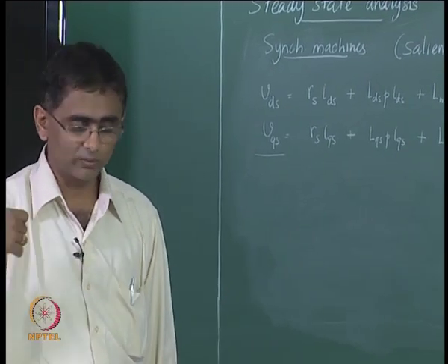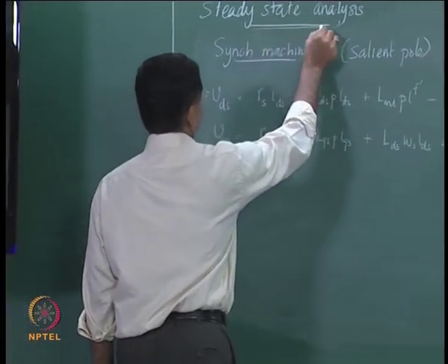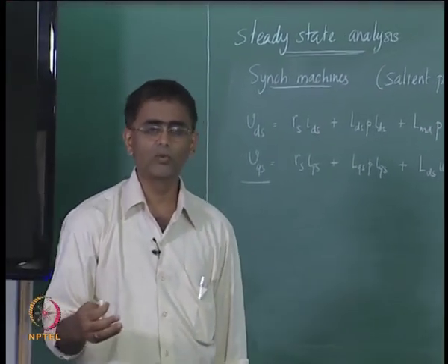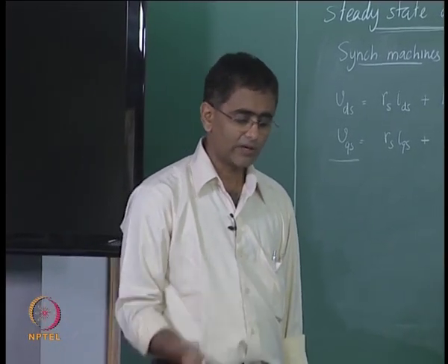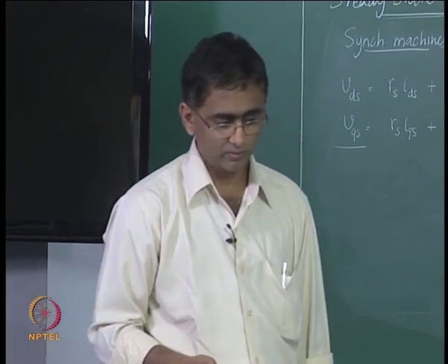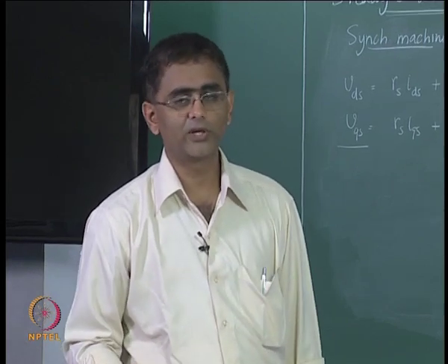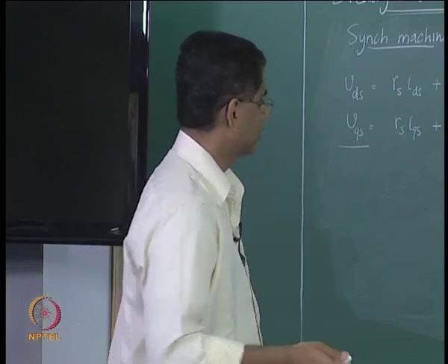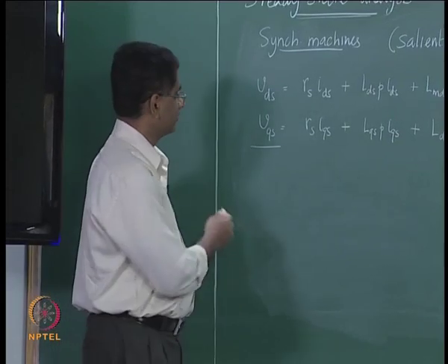The rotor is fed from the DC side, and under steady state it is going to carry a steady field excitation, which is not normally considered in the steady state analysis. In fact, if you look back at your earlier electrical machines exposure, you would not have discussed anything with respect to the field other than saying the field induces an EMF in the stator. So here also, in steady state analysis there is nothing to consider in the field, so we leave that out.